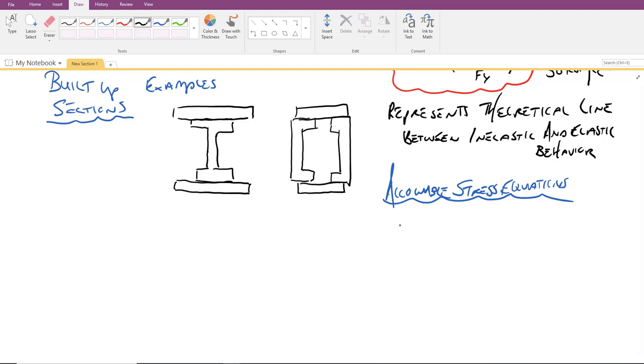It's a function of the moment of inertia. It's again simplifying two parameters down into a single parameter that we can pull from the table. And also we have an adjustment factor K that accounts for the end restraints. We'll talk more about that just in a second, to remind you what that is.